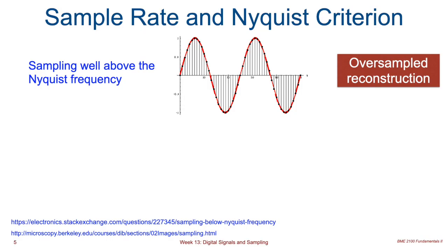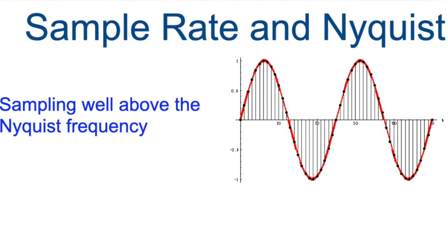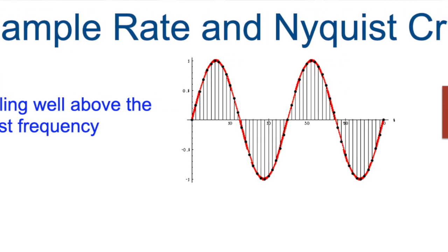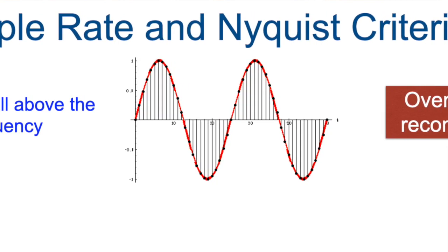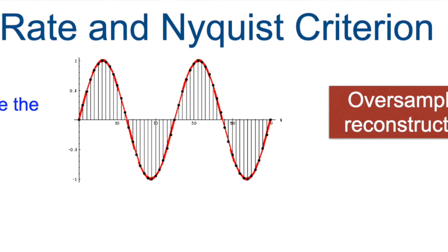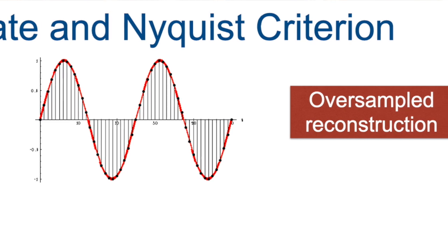Now, one of the things you've read about in the textbook, hopefully, is this notion of minimal sampling rates. It turns out that there's some wonderful information theory that was developed a century ago to understand how we can capture, and more importantly, how we can reconstruct from discrete sampled signals. So if we sample a signal very frequently, then it's not hard to imagine that we can reconstruct it pretty easily, right? There's an intuition for that. What is less intuitive is that the frequency we need to sample with is not really very high.